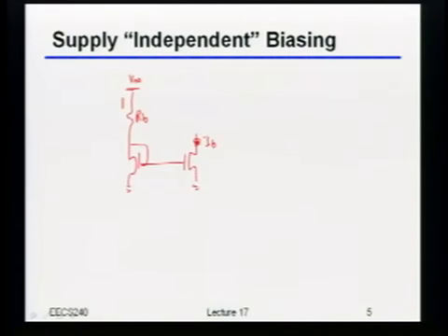Okay, so you gave me actually the small signal thing, and we're going to use that in 1 second. I'm saying from a sort of, let's say, quote-unquote, large signal standpoint. So if I told you, for example, that this voltage there, by definition, by the way, is VGS, what's going to set the current through this circuit? Yeah, so the current's just going to be VDD minus VGS divided by RB, right?